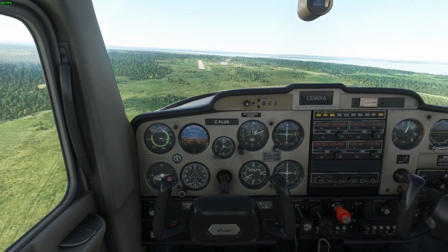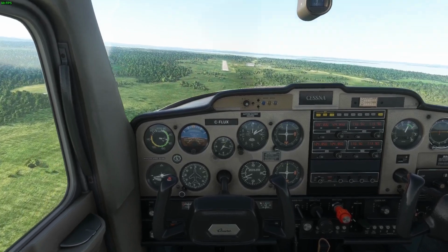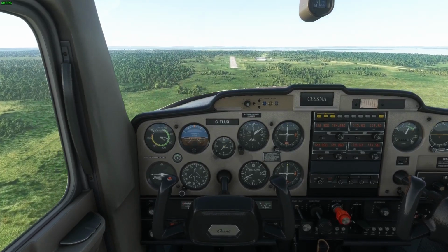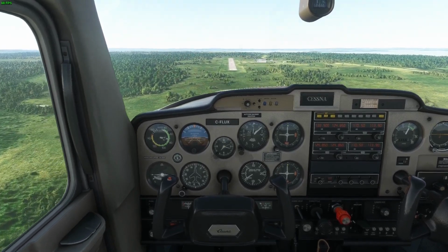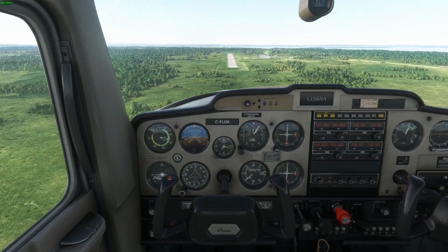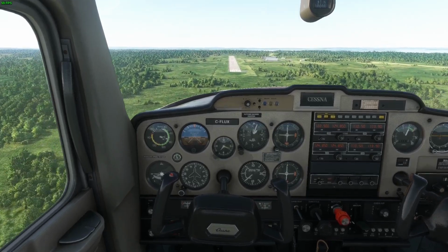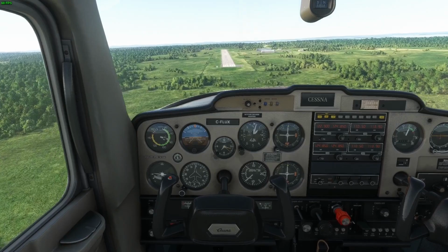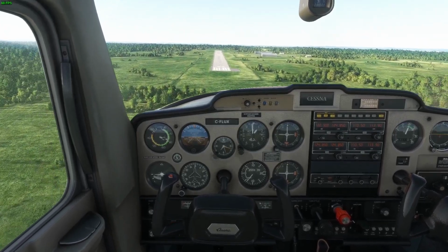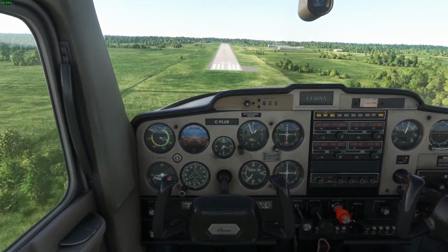Now we're lining up with the runway, best we can. Use rudder a lot here, because at a relatively slow airspeed, ailerons could induce a wing stall, so it's best to use your rudder for directional correction. Heading is good, we're in line. Well, we're a little to the left actually. Your body should be right in line with the center line, so we'll correct and pull it over a bit. 500 feet, power is good, airspeed's good, fly it right down to the end of the runway.